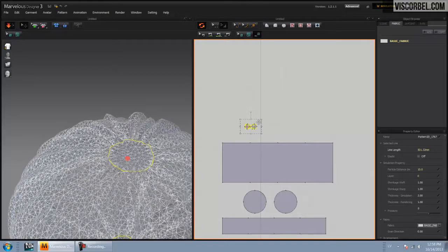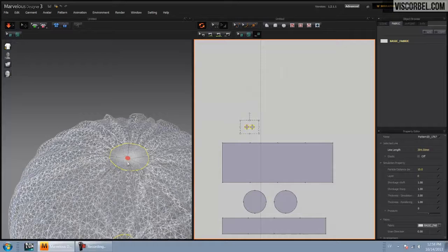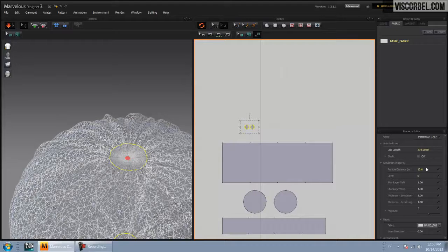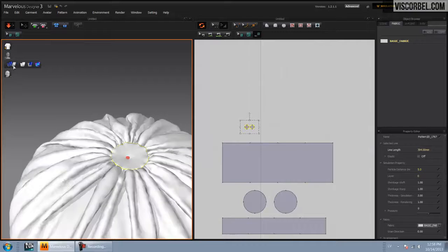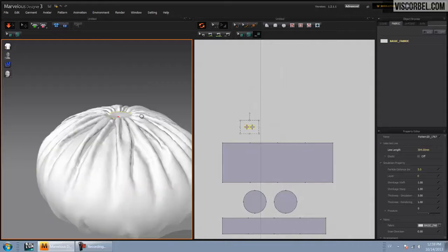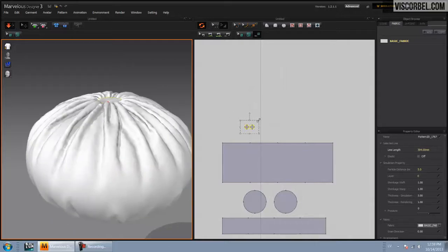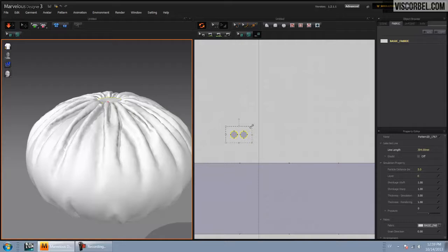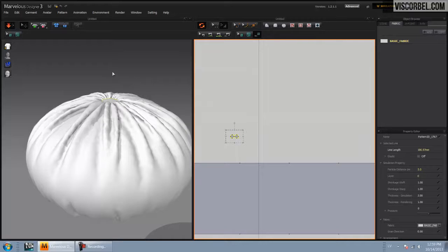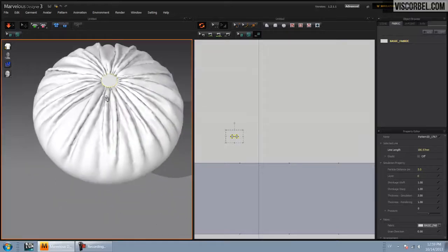Once you don't have enough triangles there, it can get somewhat glitchy. Right now you can see that the mesh density is too low. So reduce the particle distance just for those circles. And you can scale them down even more now. Alright. Just do this step by step and slowly and carefully. Okay, let's get rid of that pin. Control W. And let it settle.